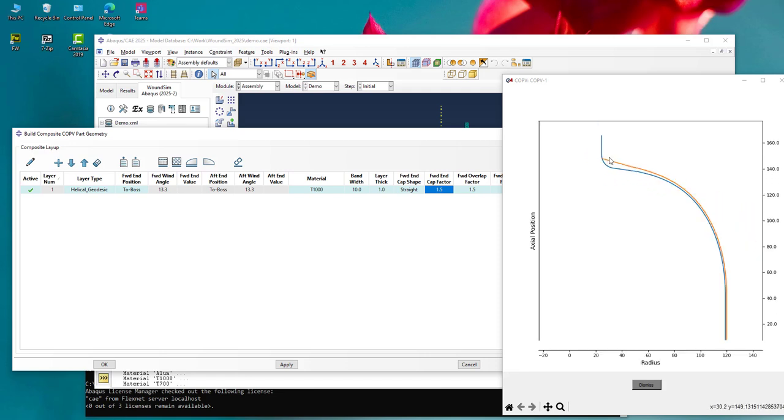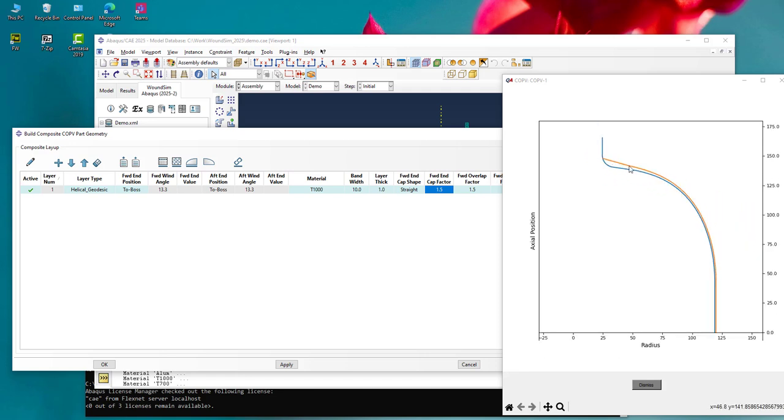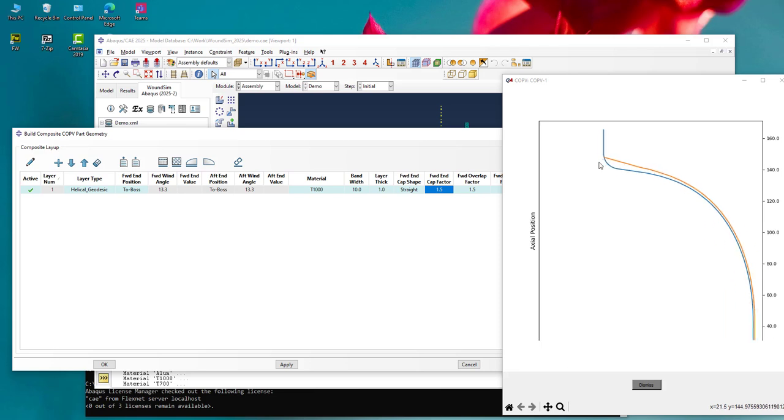So there's a layer that runs all the way up to the boss. When we say to boss, we have some equations that approximate how thick this buildup is going to be. Once we go to, let's say, 10 or 20 layers, we may start to vary from what actually occurs right at the polar boss. So we've made it very easy for you to tweak that, and I'll do that at the end.